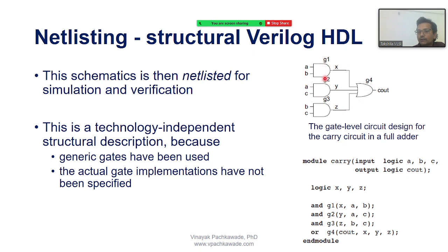The waveform for this particular logic will be generated by the EDA tool, and it would be verified by an engineer or team of engineers by analyzing its response. They will check that what is designed is behaving accordingly, meaning the behavior. They will check the timing constraints, and the tool will also generate the delay and power details of that particular logic for a given technology.